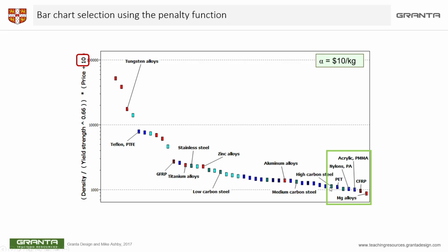They still appear on this side, but really the competition is between some exotic magnesium alloys and the CFRPs. Now, in this case the cost will be much higher than the previous case, but that's okay for us, because we have said that we are able to spend 10 times more than before. So can you see what this is doing? This allows you to take that management decision. You are saying, if I'm happy to spend 10 times more on this car, then these are my choices.